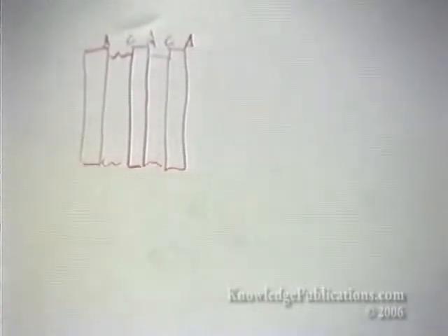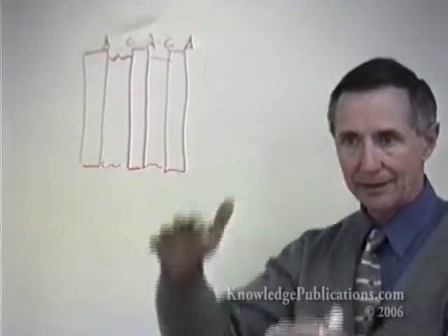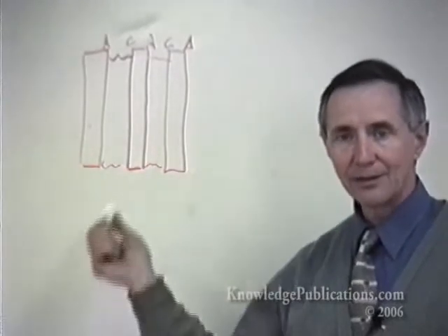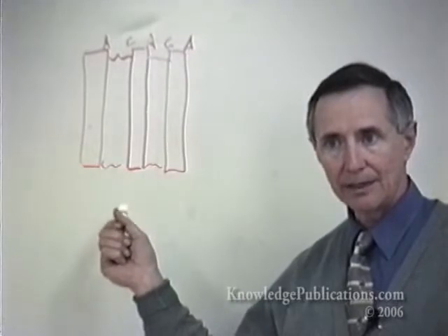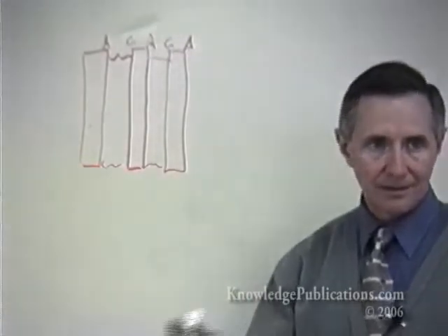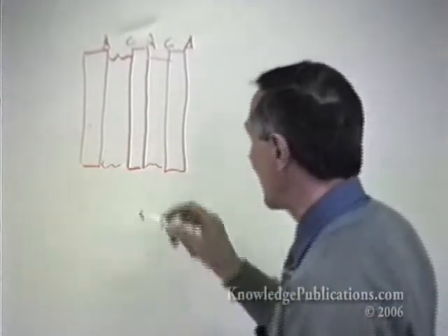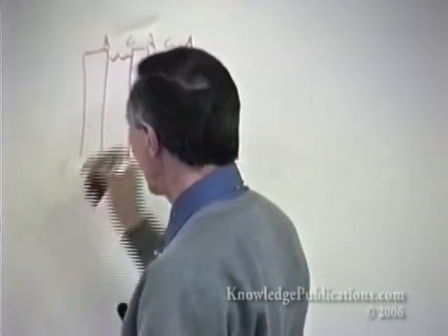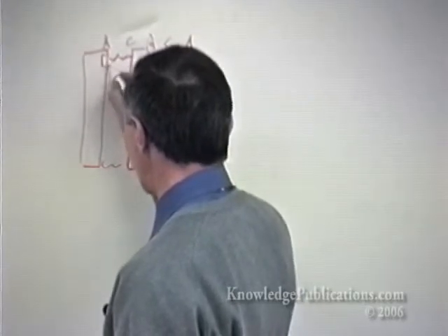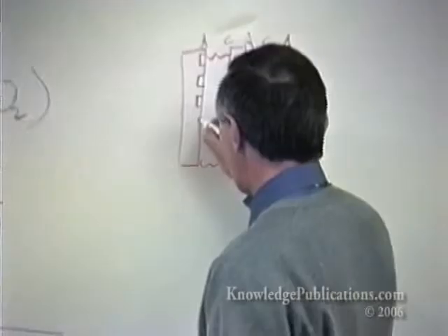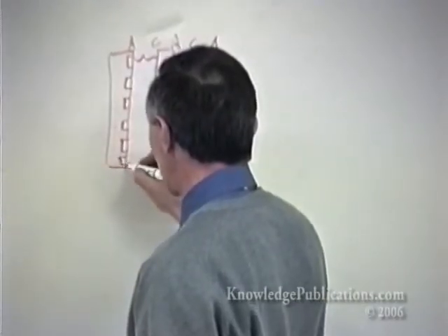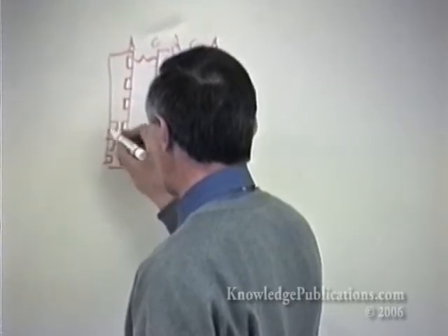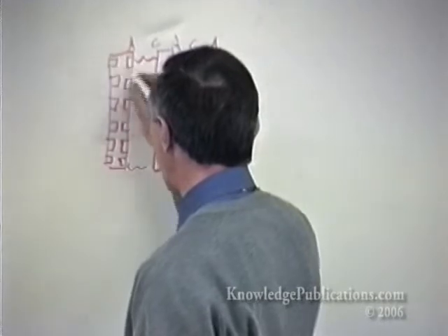Well, if you're stacking the cell in this manner to gain the voltage without having to physically connect them by external connection. That's correct. We're also making the case here that you can be very compact in terms of volume. And it turns out to be pretty well self-supporting. You can make this into units that are held in compression. Flow of gas on there? Well, this is a hydrogen air cell. The flow of gas would look like this. We'd build into this places for the hydrogen to be circulated, and similarly places for the air to be circulated on the other side of each of these flow plates.